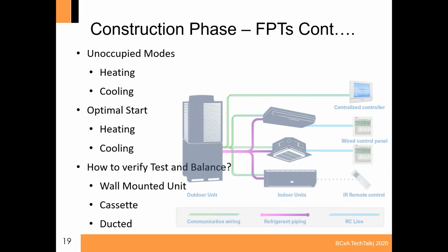And so during this time, it is still considered an unoccupied mode of operation. There should be no one in the building at this time, because the building is being heated or cooled to an occupied set point prior to anyone entering the building. So again, you shouldn't need outside air and you shouldn't need exhaust, and you're just going to test the cooling and heating modes. So once you're done with that, you can verify test and balance, and you can either verify it after your functional testing or before your functional testing.